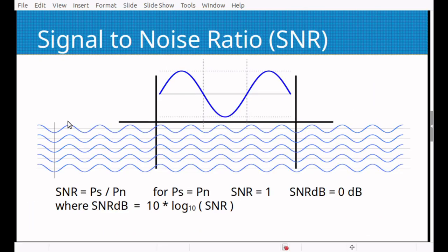So let's step back and define what signal-to-noise ratio is and how it's measured. This is a very simple diagram. We have a communications channel. There's a very specific definition for a communication channel. In the case of the primary mode I'm going to be talking about today, which is WSPR, Weak Signal Propagation Report, we're going to find this channel is only 6 hertz wide. So that channel is bounded on either side. In the case I've shown, what are called brick wall filters, but of course we can't implement them from a practical viewpoint. We'd see more of a bell-shaped curve here.